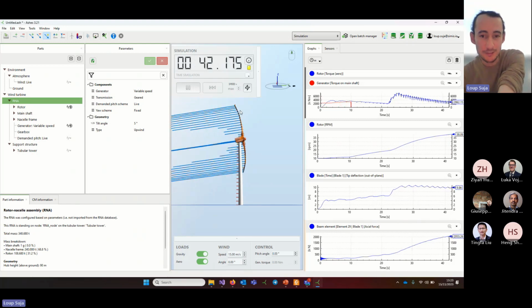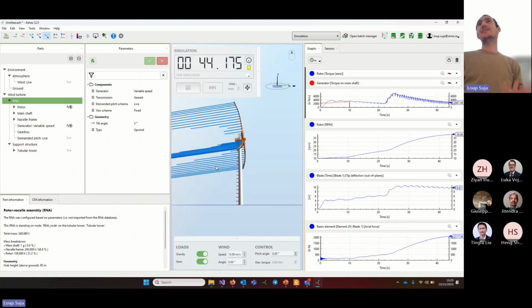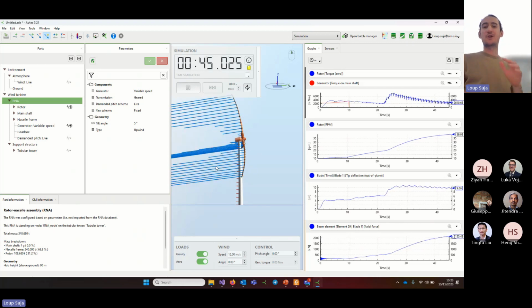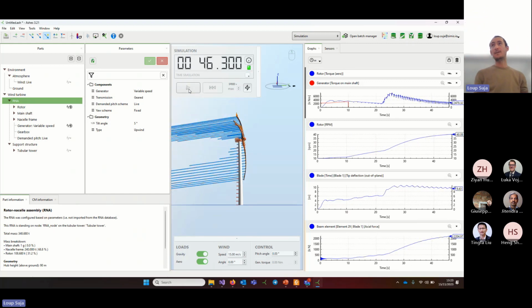Cool. So this is what happened in the video, and that should not happen. From checking Wikipedia, which didn't have many sources, so I'm not sure how much we can trust that, talking about this event that I showed you in the video, they were saying that the error was that a gear inside the gearbox broke, and then nothing was connecting the generator to the shaft that is holding the blades. So because of that, nothing was stopping it. Essentially, we just lost the torque, and then you see what happened here.